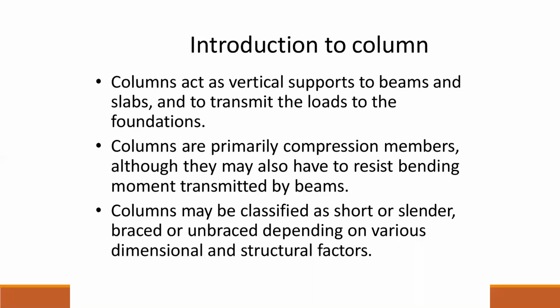When you talk about the beams, we do not design again for the axial loads because we assume that it is negligible and a very low value. But when it comes to the columns, columns are subjected to all of these: shear, axial and bending.